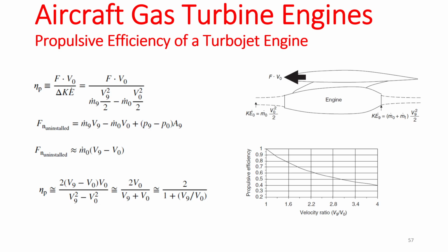That's actually the complicated part, right? You are essentially increasing thrust. That's of course what's happening, but at a very huge cost, right? Your kinetic energy jump is going to be much higher, and the amount of kinetic energy that is going to be transformed to thrust is going to decrease as you increase V9. So you're going to have a lot more losses as you increase the exit velocity. Does that make sense? Okay.